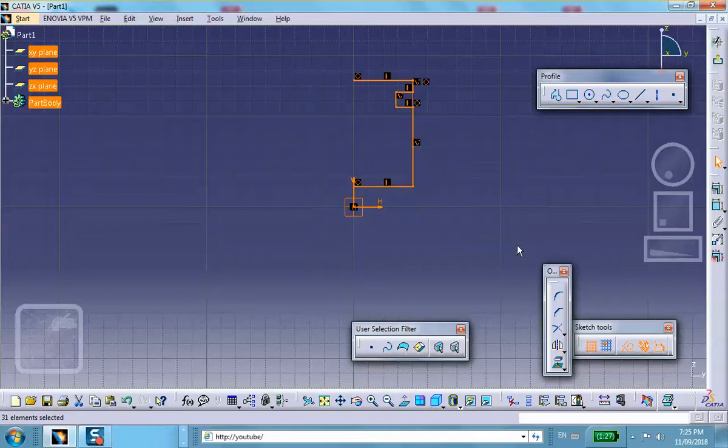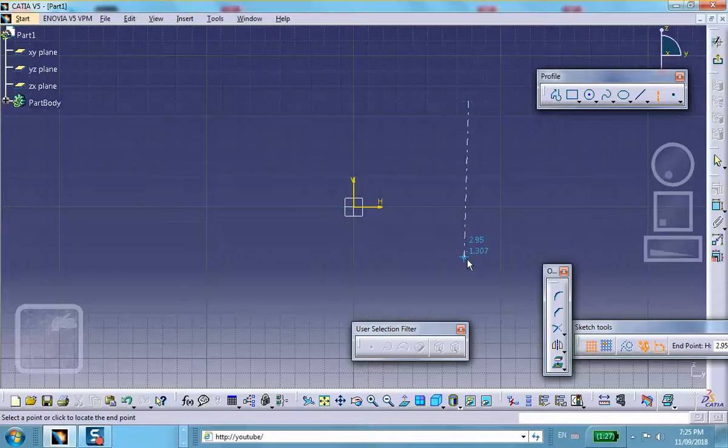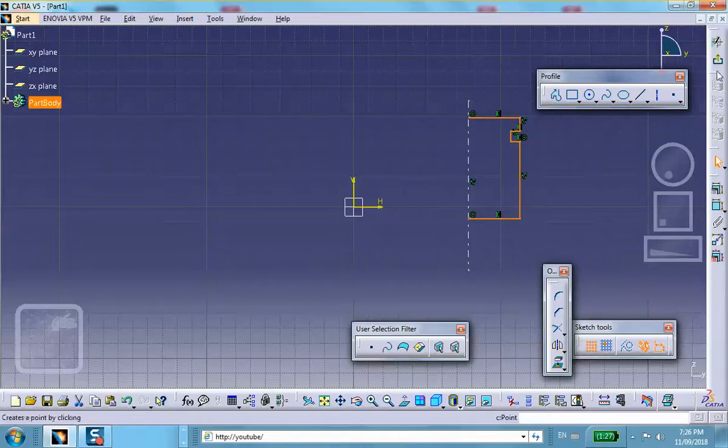In other words, instead of having this axis as the axis of revolution, I create an axis right here, anywhere I want, right there. This is an axis from that icon, and then the profile is going to be constructed here. Now, as soon as I get out of this sketch, this is going to get revolved about that line. Okay, so escape, there we are. I ignored completely the dimension, exit.